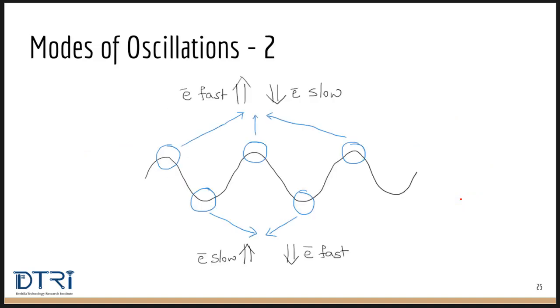Before going into further explanation, let us recall that the positive peaks of the sine wave push the electrons faster towards the reflecting electrode, while for the returning electrons, these peaks slow them down. Because the positive peaks have a pushing effect, the electron speed has the opposite effect for the positive peak and for the negative peak.